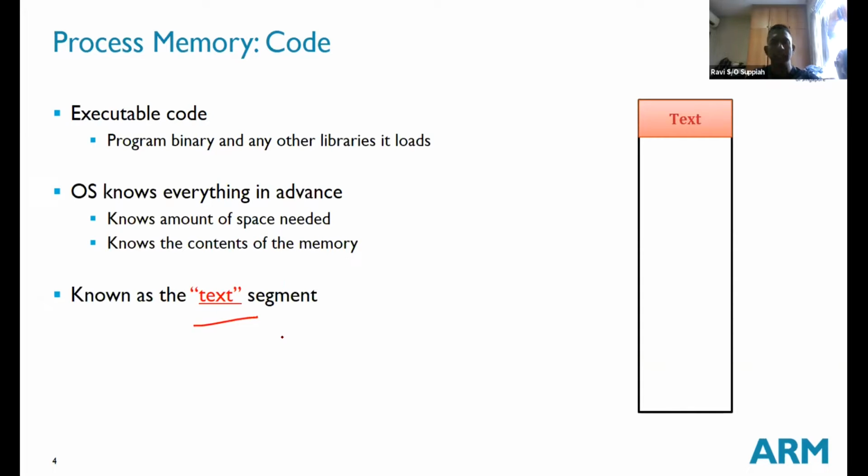In most cases, it starts at the lowest memory. That means usually 0x00000000, somewhere around there. The reason is that in most cases the reset vector of the controller will also point to that address. So you start off execution from address 0. Again, I'm talking in a general sense, but you will always come across controllers or processors that may be doing things a bit differently. But in most cases, your startup code or boot up code and all your text segment starts from address 0.